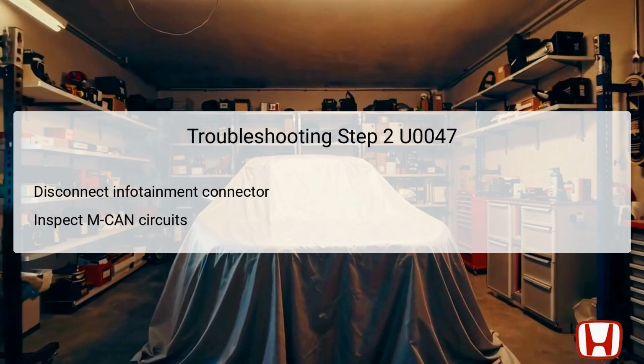It is also vital to check for potential shorts, ensuring that there are more than 1 megaohm between wires to prevent shorts that could cause further communication problems. Accurate measurement here is vital in diagnosing the root cause of the communication error.